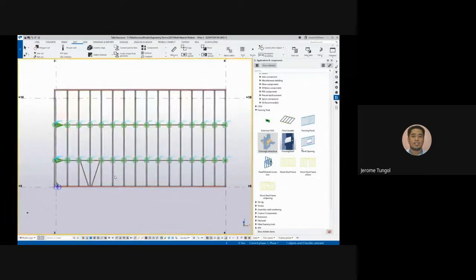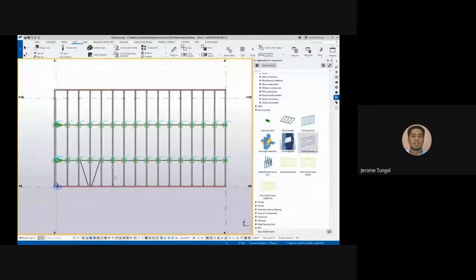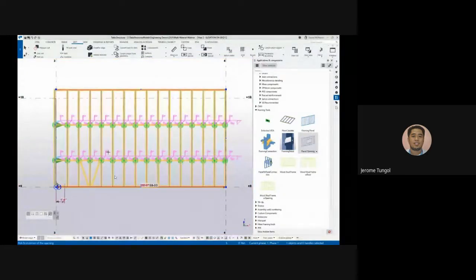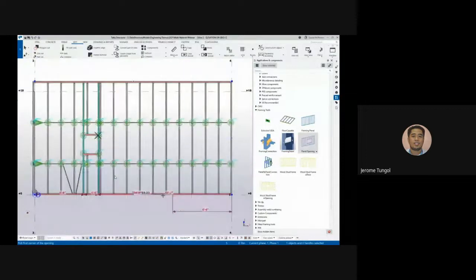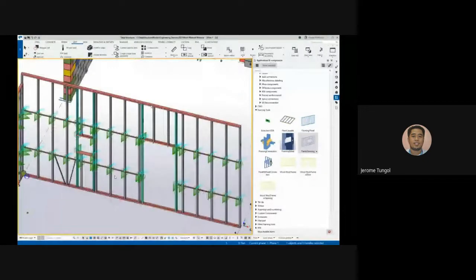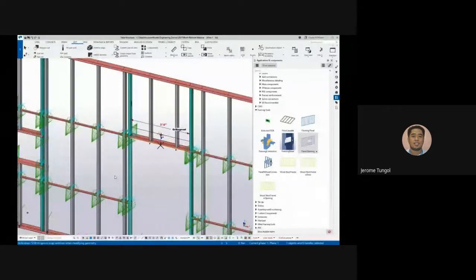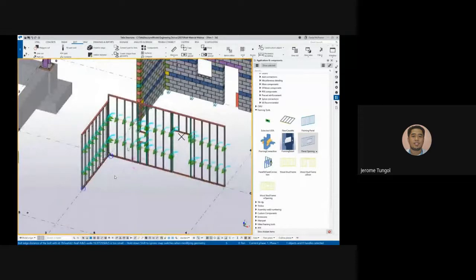And then let's input some openings using the panel opening. Again, you just simply input the size of the opening and the property or profile that you want to use. Then, again using the mini toolbar, click the reference and then the location of the openings. Once you click the right position, the openings will be shown already. So for doors, then for walls, and then also using direct modification, you can manipulate the size of the openings again. So as simple as that, you can have your metal framing. Then we will quantify it later on.